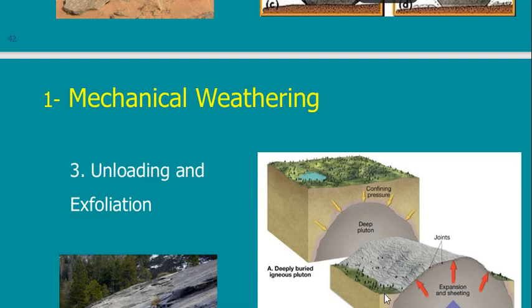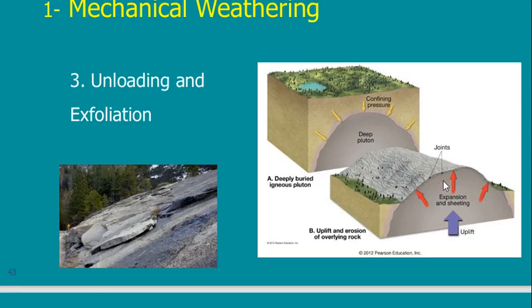This is what remained from the sedimentary rock, and of course, because this is an igneous rock, it is stronger, so it stayed in place. But due to the effect of the unloading that happened to this rock, the surface layers are going to be exfoliated, as if you are taking layers out of it, layer by layer, till it is eroded itself.